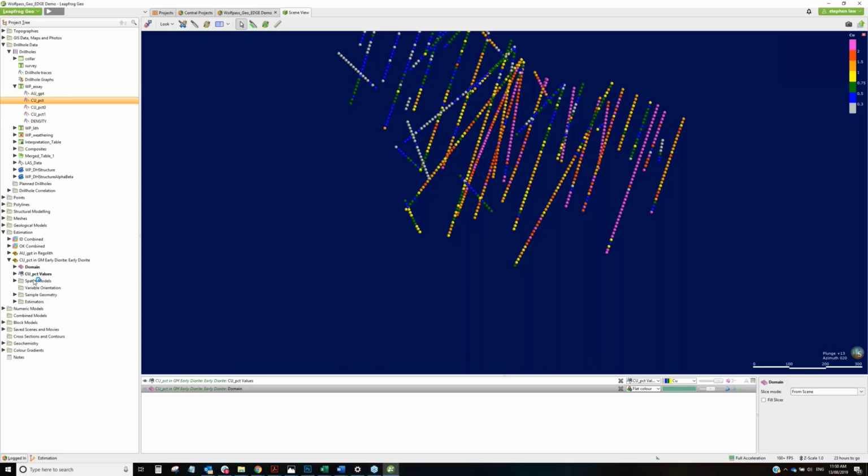Spatial modeling is our wording here for variography, so we'll have a look at that in a moment. We now have a variable orientation functionality, and this is like locally varying orientation. So this is where the search ellipse actually changes relative to a particular guiding mesh. So if you've got, for example, an undulating layer, then we're still restricted to a variogram in the sort of global trend of that. But as we search for our samples, it will vary the orientation of that search ellipse, taking into account the underlying variogram, and you potentially have better selection of samples. We'll have a look at that a little bit later.